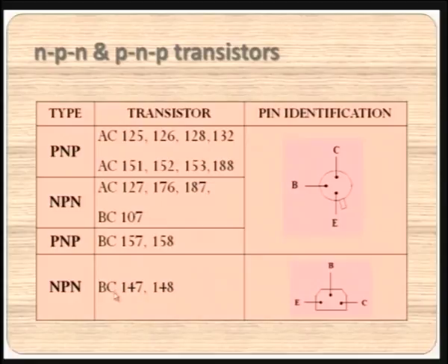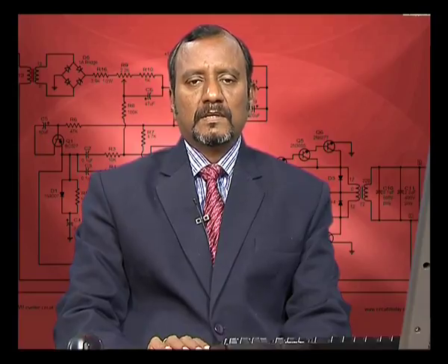And here we have another set, an NPN transistor, and this will have a flat shape. Again, the typical bottom of the transistor is shown here, and once a triangle is formed, the one vertex in the middle is the base, and the other two are emitter and collector, for which we have to hold the transistor in the particular position as shown in the diagram. We have to hold the transistor in the particular position to identify the base, emitter and collector terminals.